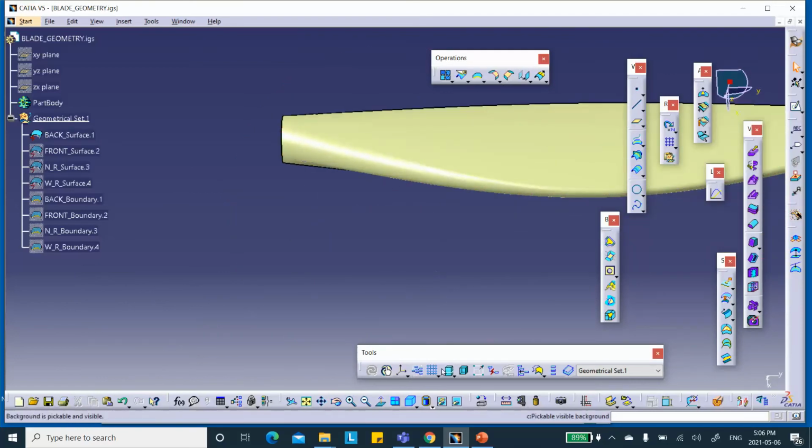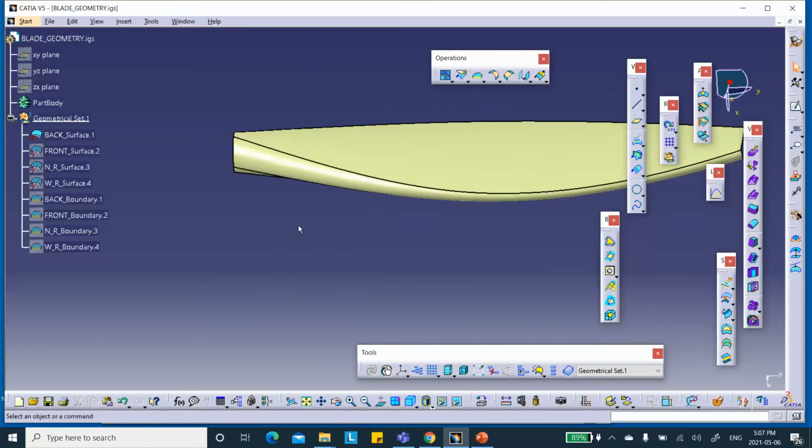As a matter of fact, if I change the rendering here, I can see that better. So let me see now, maybe with the edges. I want to extract this boundary here because I want the rosette to basically follow the x-axis.